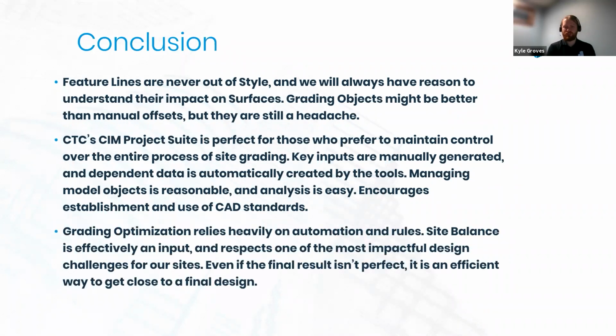As far as grading optimization is concerned, it does rely heavily on automation and on rules. Your site balance is effectively an input at this point, which is a game changer for how we put our designs together. It's one of our most impactful design challenges in the real world. Even if our final result isn't perfect and we're not going to submit that as part of our plans, it's an efficient way to get close, or at least to say, well, I definitely don't want a berm over here, or I am going to need to find a spot to build up a 3-foot berm just to take care of some of that cut.